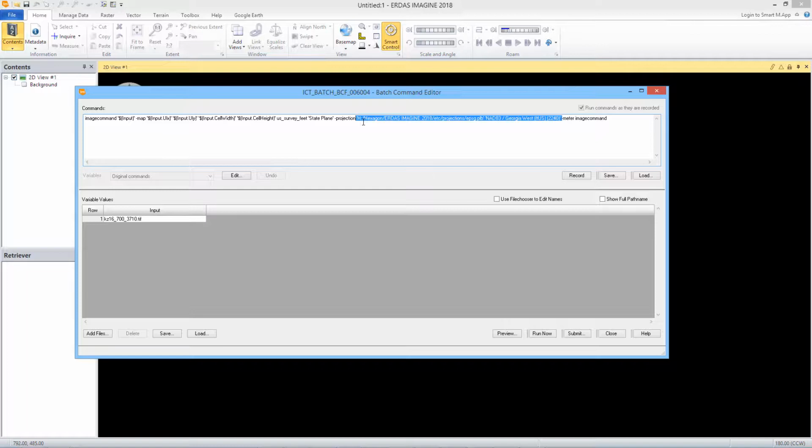In versions prior to Erdas Imagine 2018, this would not have been the case. The command would have required manual creation of variables and their insertion into the command. Often this resulted in mistakes in the command and images with the exact same upper left corner coordinates being written to them, and therefore effectively corrupting your original data. Erdas Imagine 2018 streamlines the process and only hardwires the values which we actively changed in the dialogues that we accessed earlier in the image command tool.